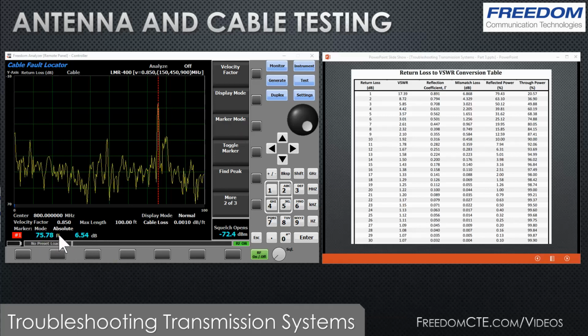From the manufacturer's data sheet, we know that the cable loss should be approximately 0.044 dB per foot. Multiply that, we get 3.33 dB. Now remember, the signal's going all the way to the end of the cable and coming back, so it's actually measuring twice the cable loss.